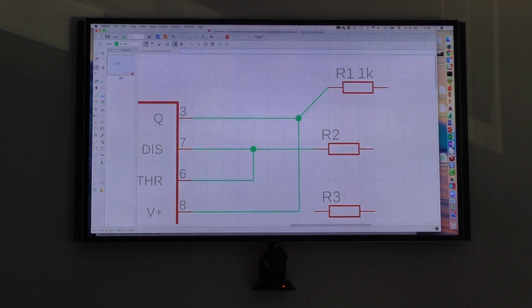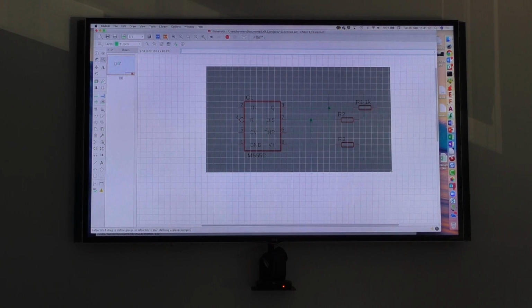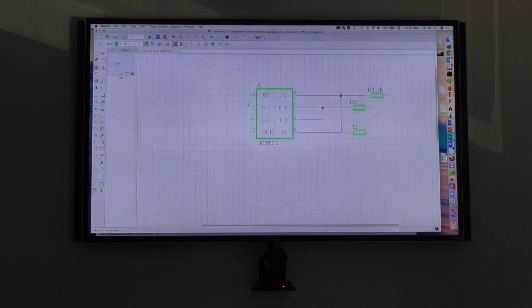Moving something, you have the move command, click on it. You see, you can move it. I can also move a group. Use the group command, click on it. I can simply drag a rectangle around all the objects. You see, it's highlighted now. And now I can simply click onto one of these elements and move it, and click and drag it away.